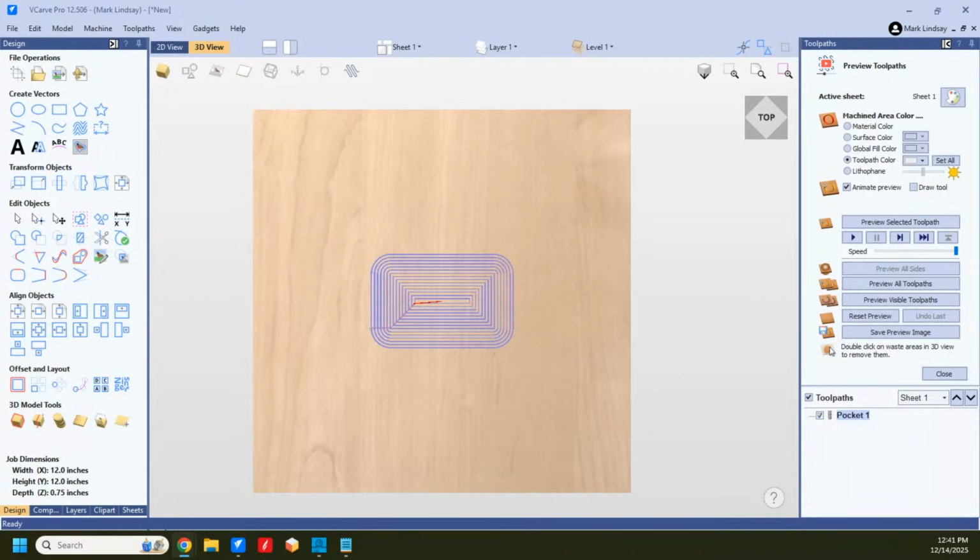So it depends big time on the material. But I'm comfortable enough in knowing my speeds and feeds that some materials I can cut at a pass depth equal to the diameter, but not necessarily.